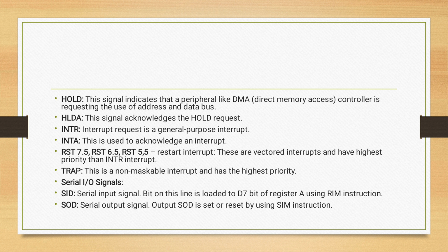The microprocessor acknowledges the interrupt signal and issues the INTA signal after receiving the INTR request. So the INTR is enabled or disabled by software. An interrupt is used by an IO device to transfer data to the microprocessor without wasting any time.